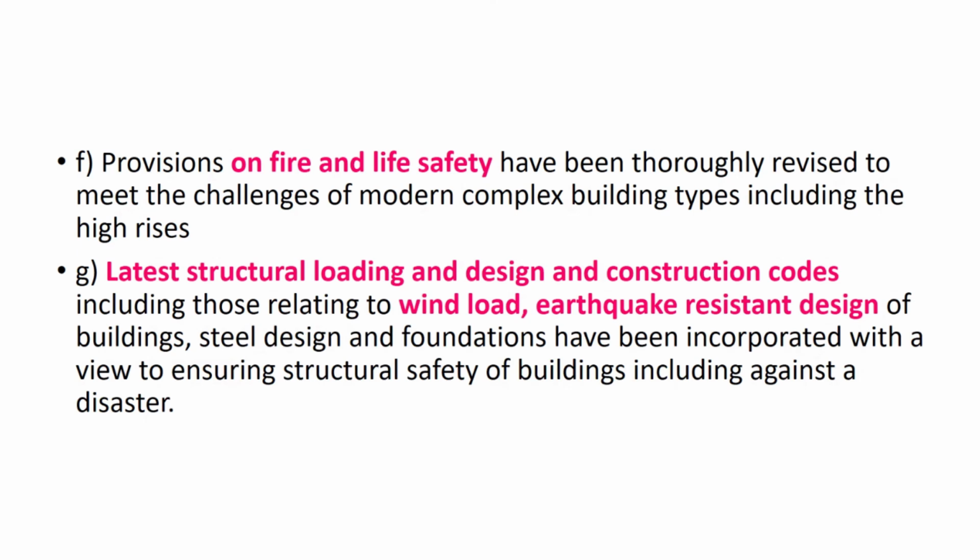Now what is my remedy? In case I want to have this facility, then my structural designer will cater to this requirement. Are you able to understand? The structural designer will make a provision of having a 4 inch dia hole in between my structural member. Then possibly, according to design, he will see removing that particular cross-sectional area from the beam, whether it will be safe or not, or he will increase the section of the beam, or he can provide you an alternative location from which you can take.